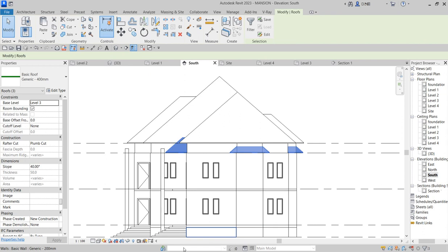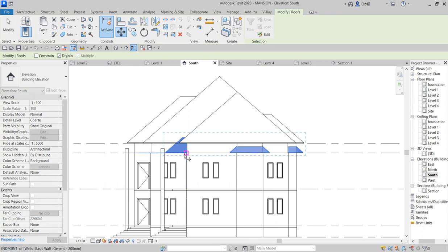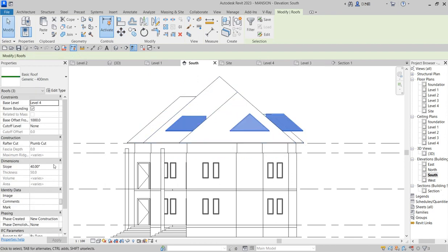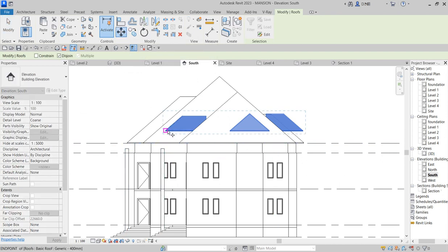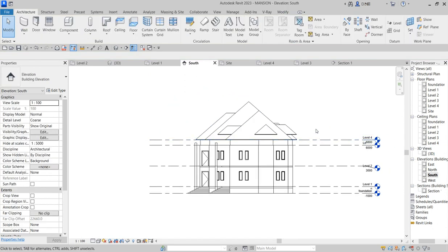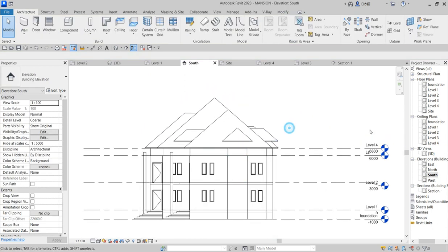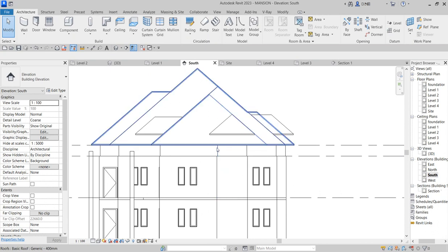So what you do is that you push them up. You just copy from here and you bring them to like 180 or 190. Just say 1800. Press enter. So it's too high for me. What you just need to do is to bring them down again. Move down to like, just say like a 250. Okay, I think they need to come down. So that's how you do that of lifting the roof system up.